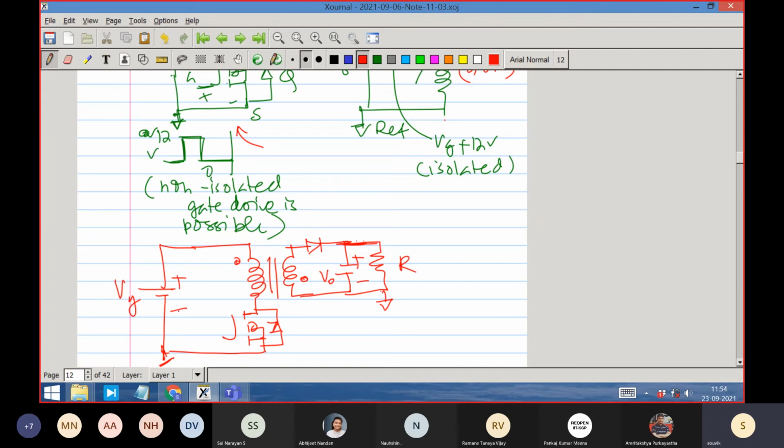So this is what it is. However, one very important thing which we have not discussed is that whenever there is a coupled circuit, there is a leakage inductance, and that leakage inductance creates some sort of problem in the circuit. When this Q is on, and when you suddenly change, the transformer primary's leakage inductance still wants to, the part of the inductance that is coupled to the secondary. Suppose this part of the inductor is coupled to the secondary. This is a magnetizing part.